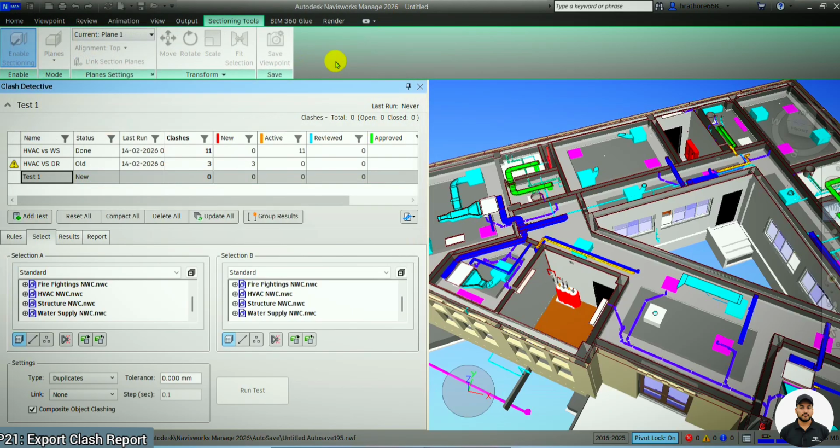After that, the same member can open a new Navisworks session. He doesn't need to manually set up those clash metrics again. He can simply import clash tests from the file that you have shared with him. So this is how you can share the clash tests, or clash test metrics, whatever you have added here, with your teammates.